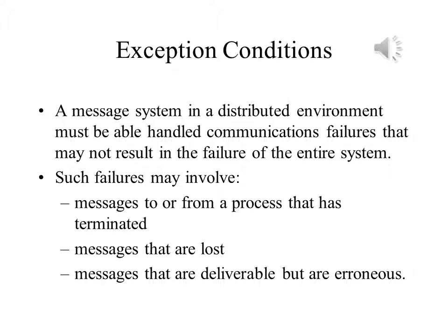If the message is received, it is possible to check for errors using either parity, cyclic redundancy check, or another error detection code. If an error is detected, then we can request that the message be sent again. Some codes may even allow us to determine what the error is and to fix it. While these coding methods are more expensive to implement, they save us the trouble of retransmitting a message.